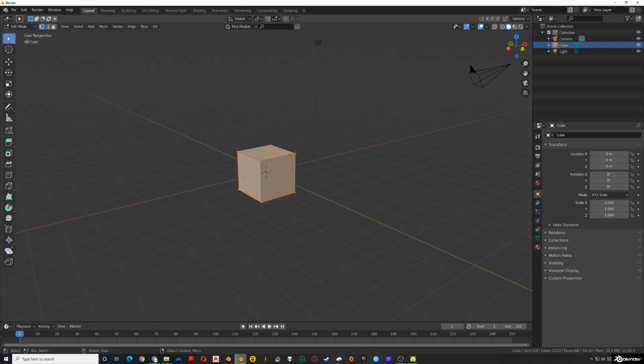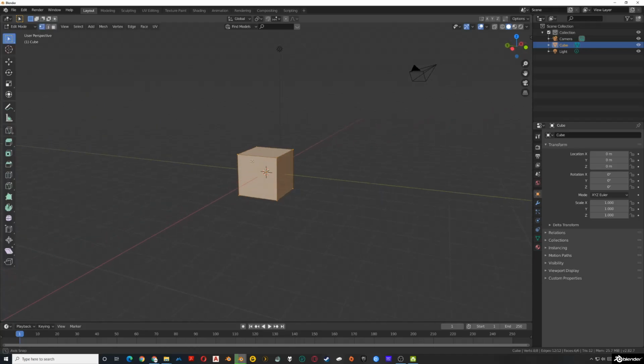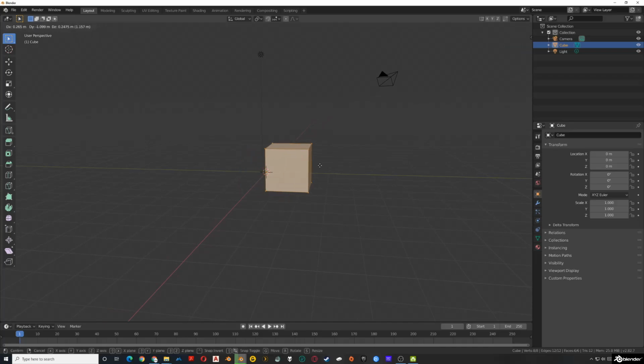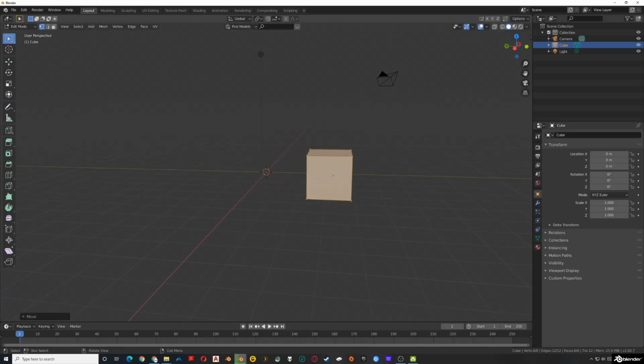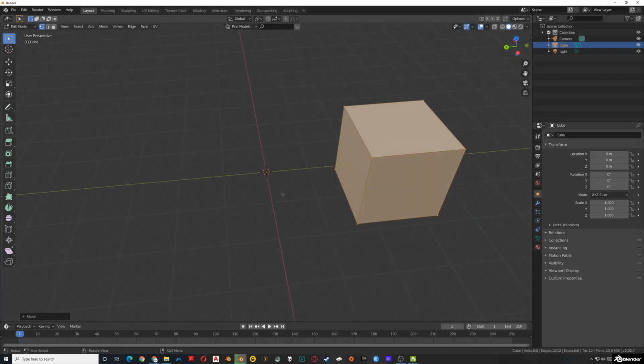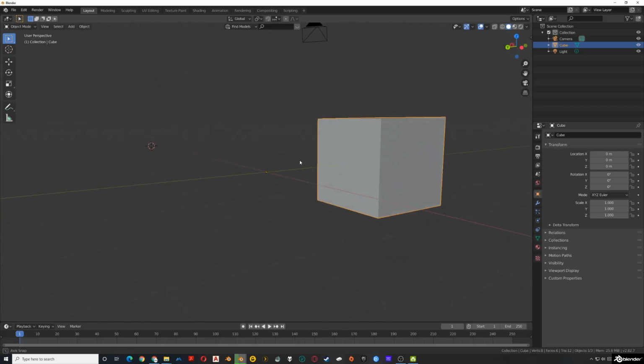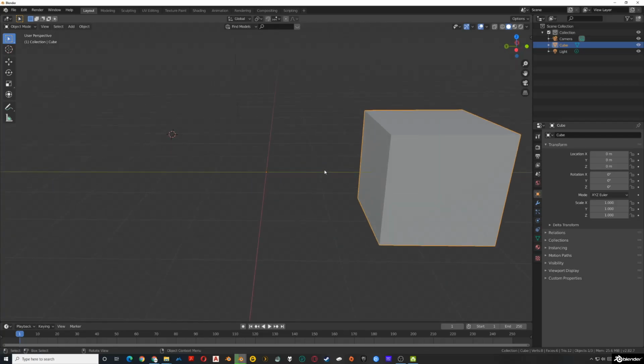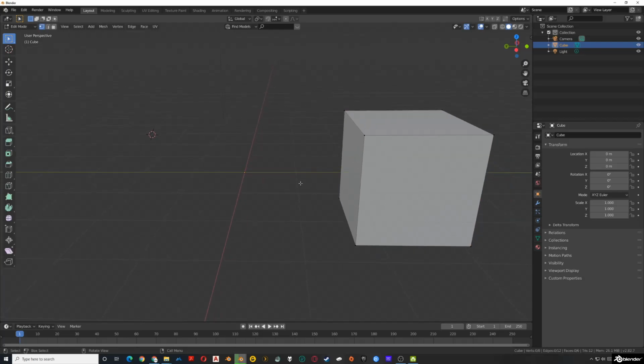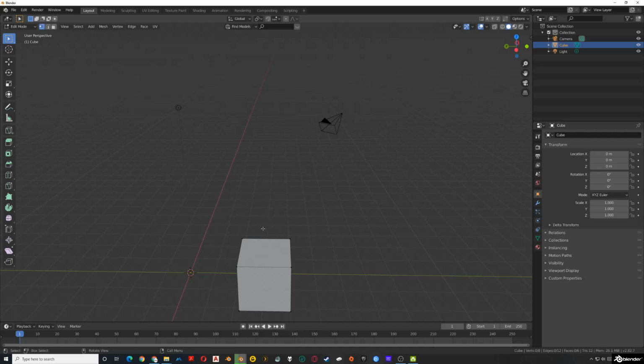All right, so edit mode. You can also hit tab. And first I'm going to move this over. The reason you don't want to do this in object mode is because you'll see a little orange dot. And if I move that, you can see it even better. There's a little orange dot there. That's called our origin. And when we do our mirror, we're going to mirror it across that origin.